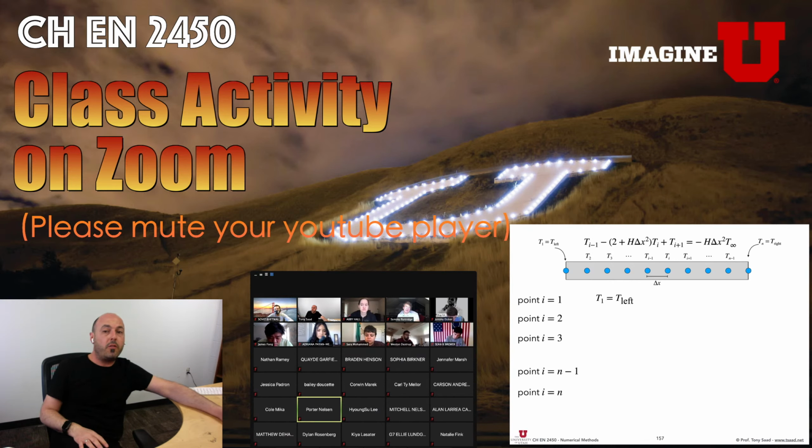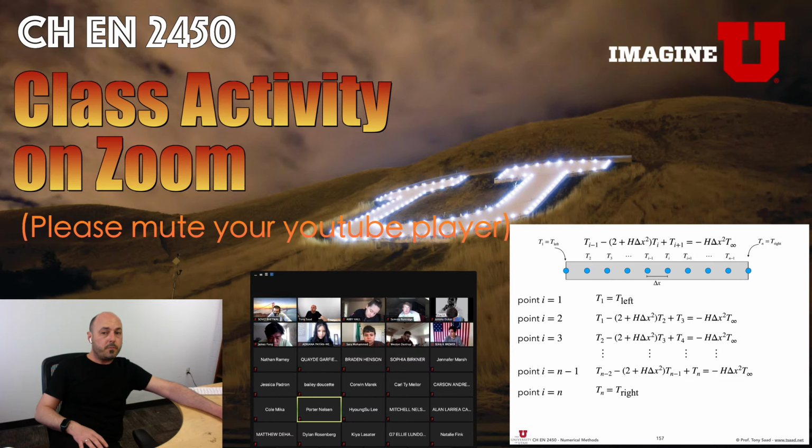At point 2, you apply the equation, you get T1 minus 2 T2 plus T3 equal minus h delta x squared, and then T2 minus 2 T3 plus T4, and so on and so forth, all the way to point n, where Tn is equal to T right. Now, don't be dissuaded that we don't know T2 and we don't know T3. Of course we don't know them, but that's the goal. We want to find them. But now we have equations that contain all of those unknowns, T2, T3, T4, T5, etc. And we have enough equations to solve for all of those, right?